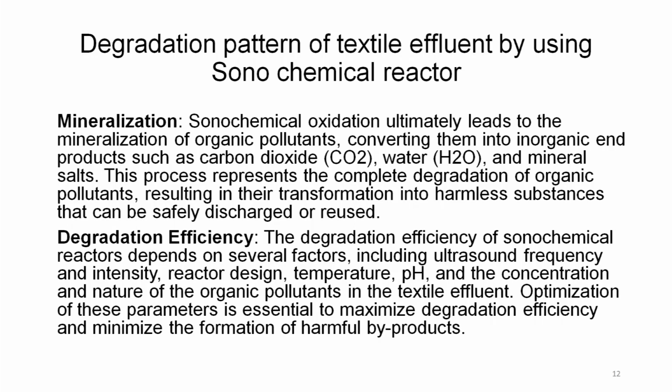Degradation efficiency. The degradation efficiency of a sonochemical reactor depends on several factors, including ultrasound frequency and intensity, reactor design, temperature and pH, and the concentration and nature of organic pollutants in the textile effluent. Optimization of these parameters is essential to maximize degradation efficiency and minimize the formation of harmful byproducts.